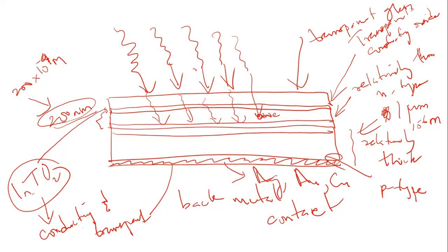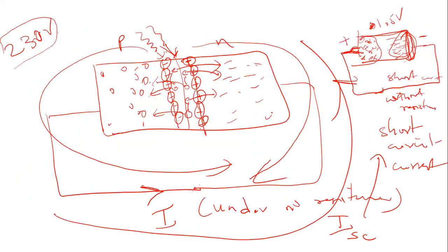But within this n-type here, there is no potential barrier, isn't it? If light falls on this n-type, and when this photon energy, that is h nu, is greater than the band gap of this n-type semiconductor, this light photon will be absorbed. When the light photon is absorbed, an electron and hole pair will be formed. But these electron and hole pairs that are formed will momentarily be formed and they will momentarily recombine. They will recombine again.